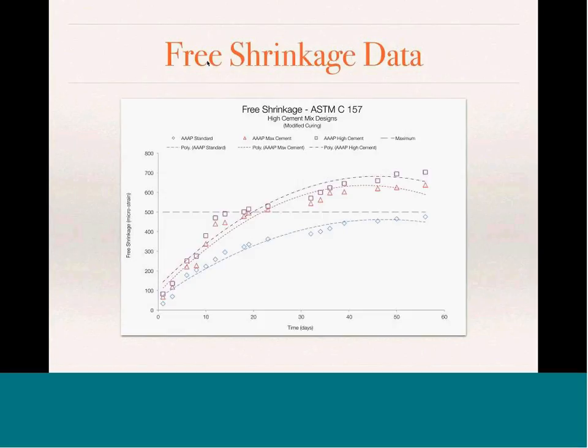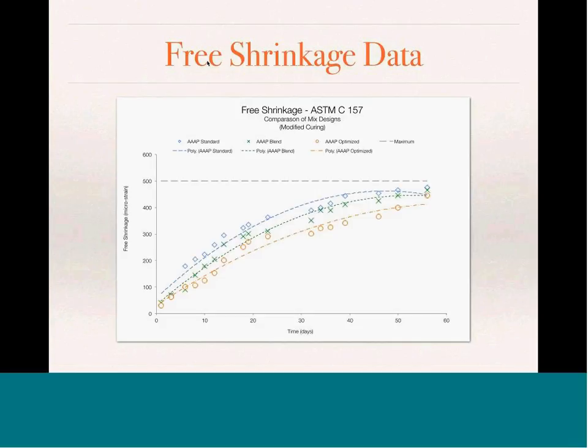So again, shrinkage data: the purple line, 800 pounds straight cement. The next line is the maximum at 690 straight, and the AAAP with 600 total cementitious, 35% slag replacement. That's a substantial improvement. That's where we're at with AAAP. We just wanted to run straight cement mixes to see how they stacked up against the AAAP, and we knew AAAP would be a big improvement.